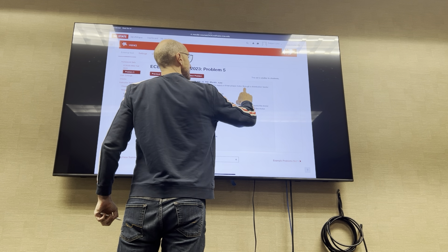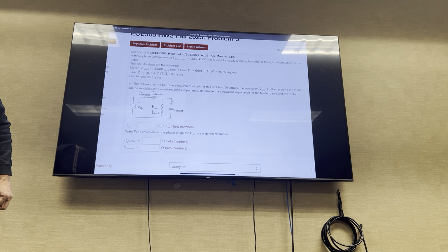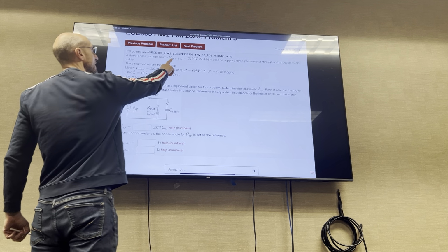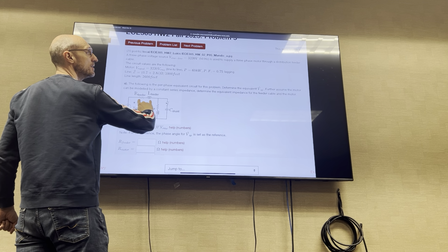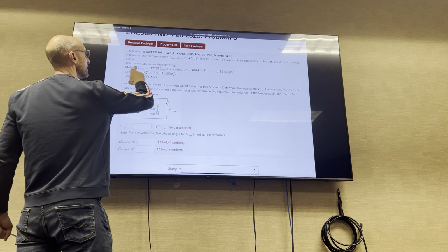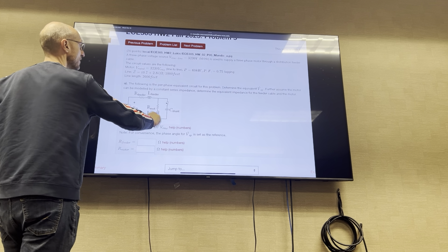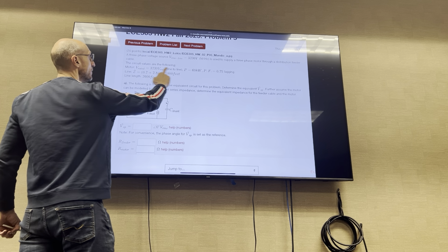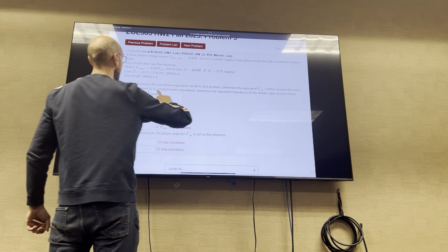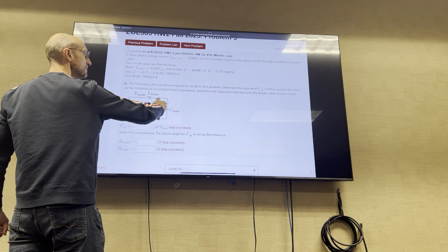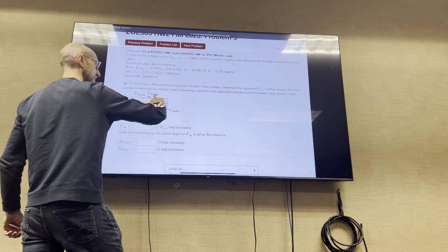When you can, used to supply a three-phase motor through a distribution feeder cable. Let's see if I can make this whole thing a little bit bigger. So three-phase voltage source supplying a three-phase motor through a distribution feeder. We're given circuit values, V rated. This is the voltage source line to line. So for this per phase equivalent, I would divide this by square root of 3. Power is always given as a three-phase value, so the power and the power factor are given for the motor. Oh, this is the rating of the motor, sorry. So this is the power and the power factor of the motor.